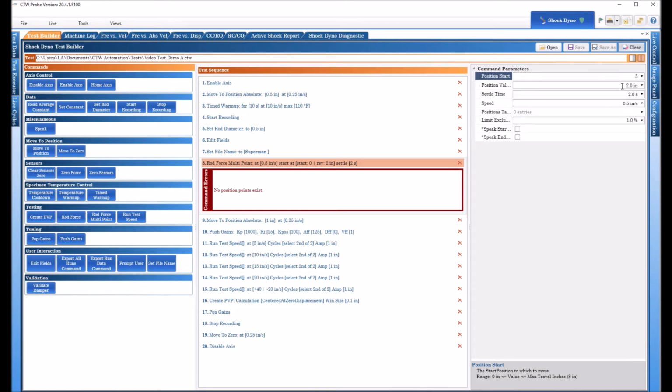So that is basically the bottom of your stroke, and let me help you out so you can actually see. Look at that. So the position wave reversal, that would be the top of the stroke. So if you started at a half and you wanted a 3-inch stroke, then the top would be 3.5 inches. So that would cover the 3 inches of stroke, and you're a half an inch above zero.